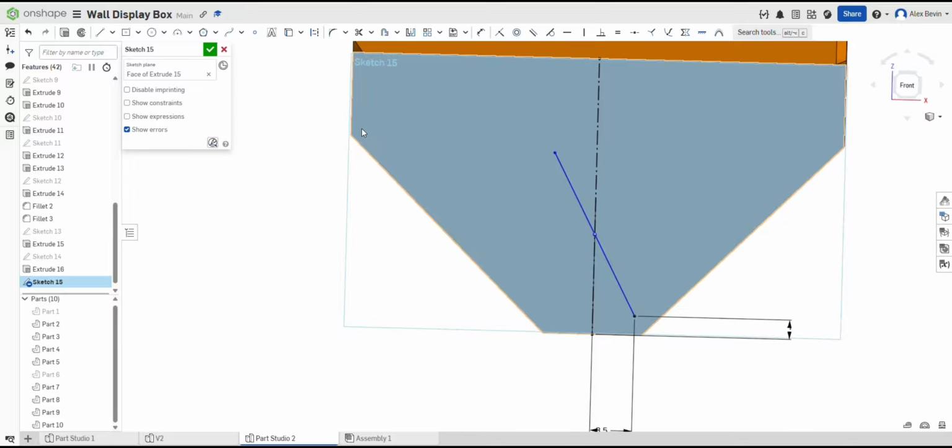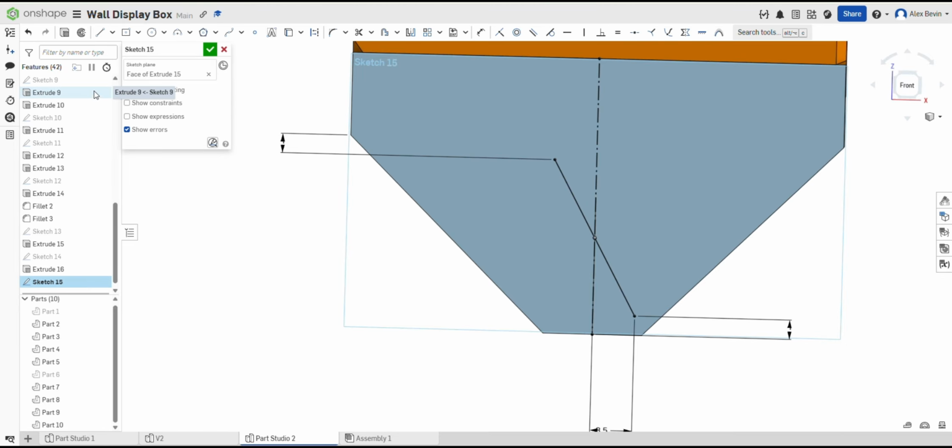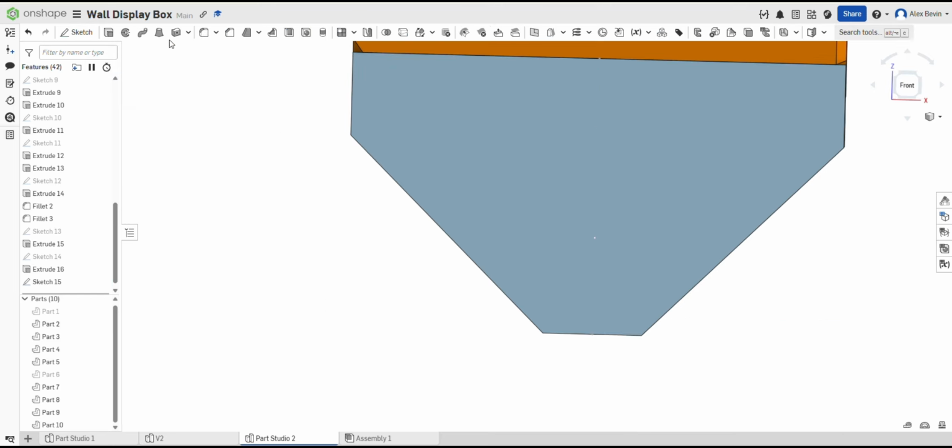Section C. Chamfers and fillets. Rule: keep wall faces flat. Now we'll soften edges, but only where it makes sense. Here's the rule. If a face touches the wall, keep it flat. Only chamfer or fillet edges that don't touch the wall.